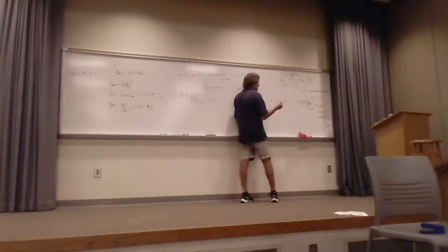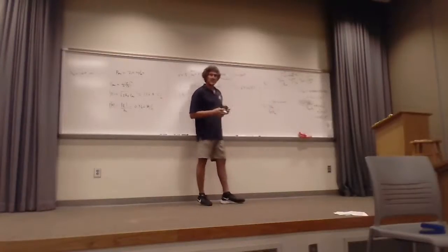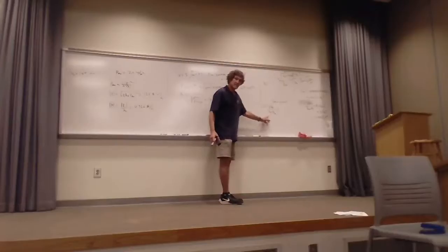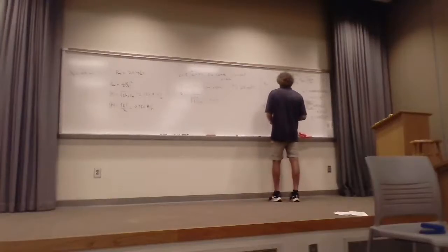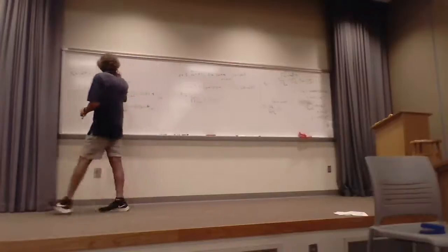Now tau 2, I'll do it right here. Tau 2 will be twice the impedance you're going into over the impedance you came from plus the impedance you're going into. Y'all remember what I said this is going to be for good conductors? About 2, right? Because here, eta shield is so much less than eta naught. Eta naught by eta naught cancels, you get about 2.